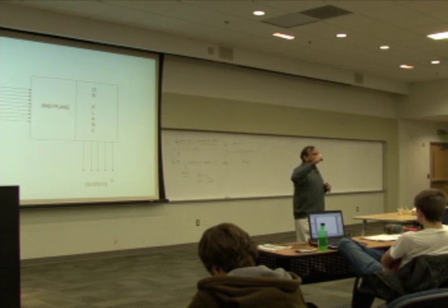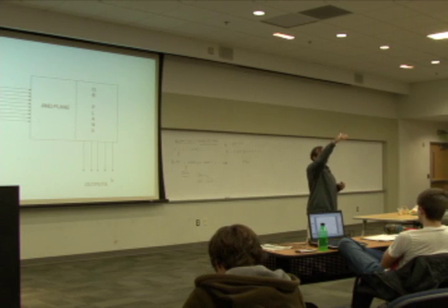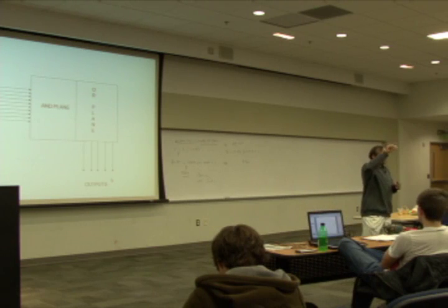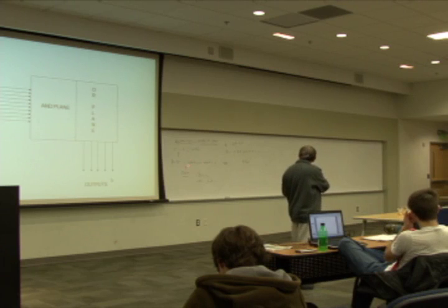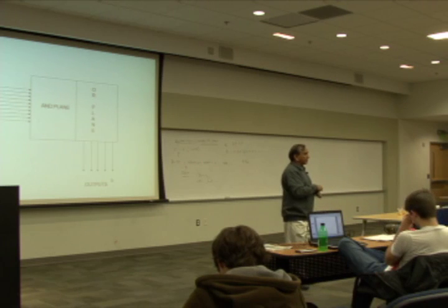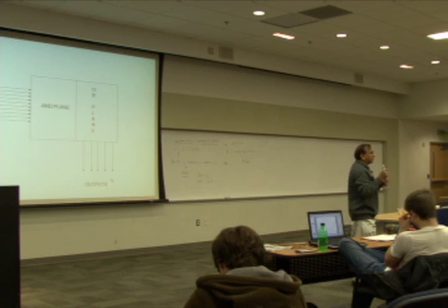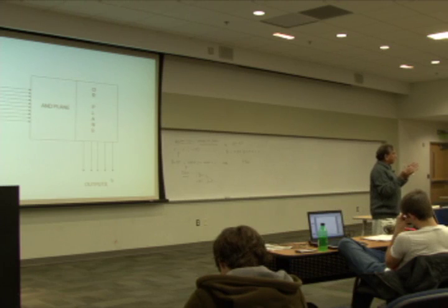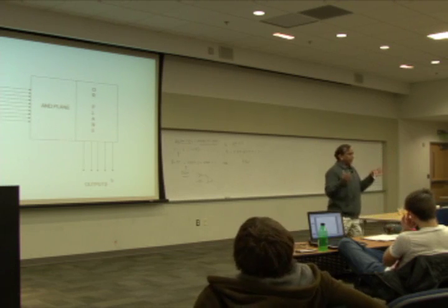And this goes back to what Ryan was saying about the hardware resources. We're using a whole bunch of hardware resources to store zeros, which we don't really need. And one of the nice things about the hardwired design is that it has exactly the number of gates needed to represent this particular function, right? And so it is more compact in design, and it goes back to what Peter was saying about the speed advantage. When you have a compact design, it also results in higher performance.